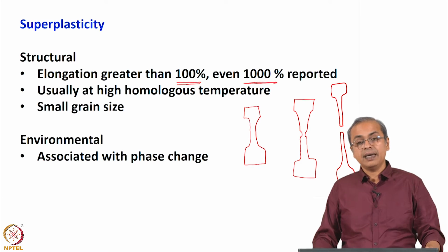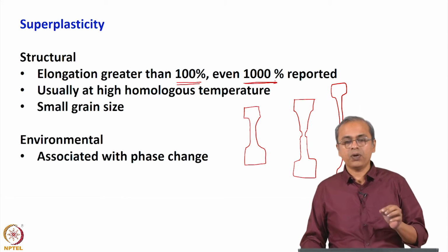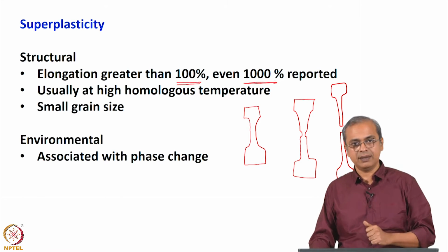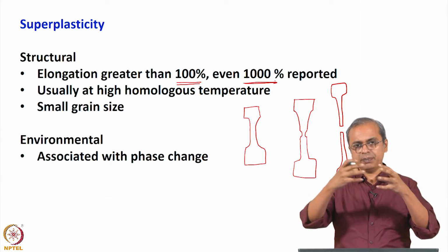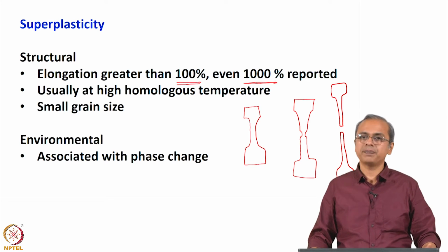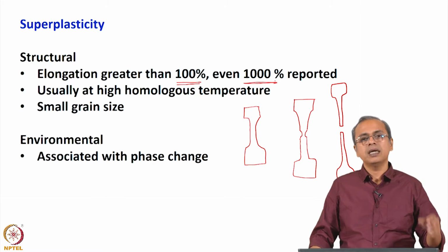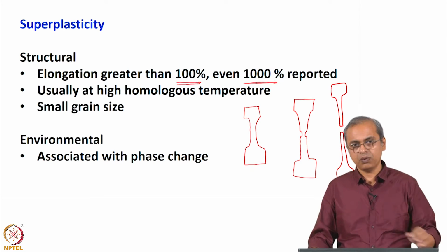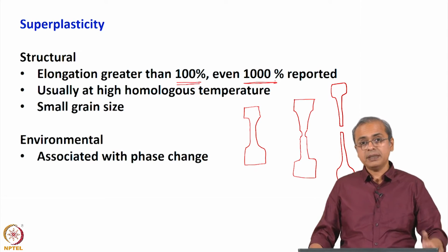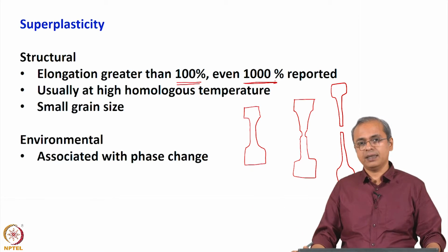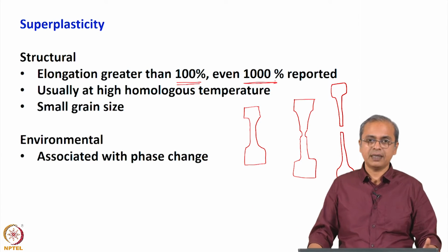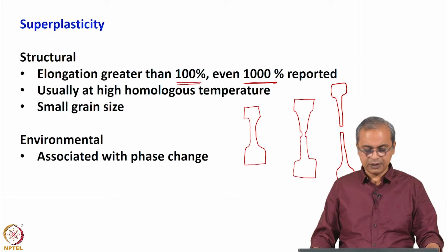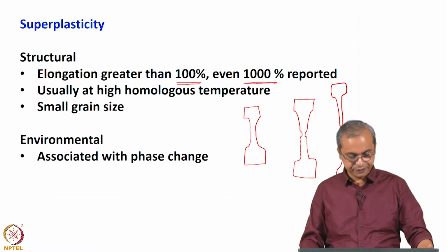And in all those cases, it is very important that the final shape is obtained without fracturing that material, right. So some complicated shape you want, some deep cup that you are trying to form, and so on. You want that whole thing to form without a crack in the cup or some broken part of that cup. So that means it has to continue to plastically deform in that range over which you are deforming it, and that is where this superplastic deformation process really helps us.